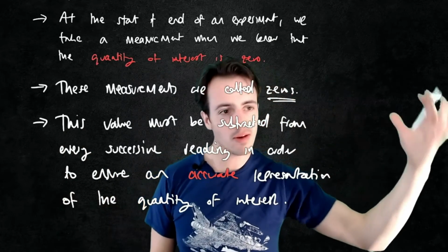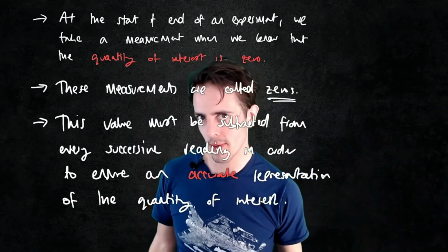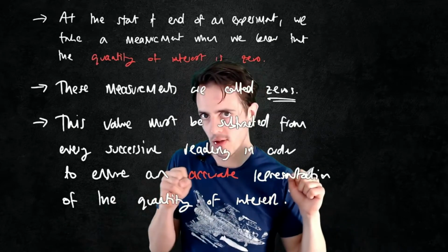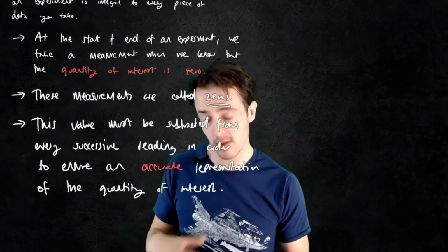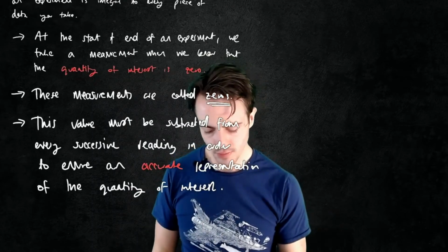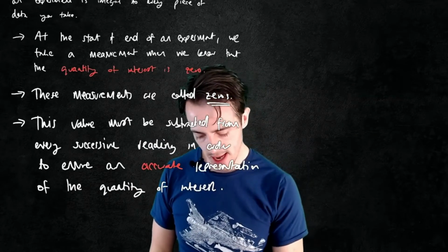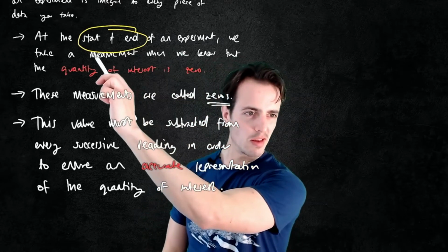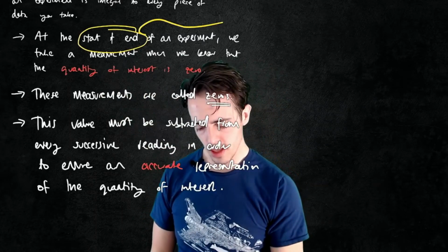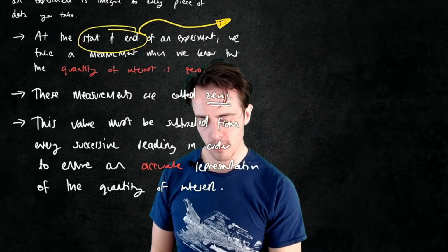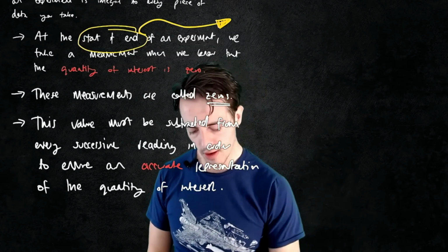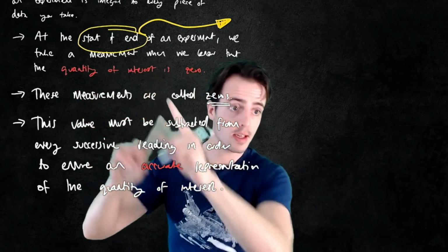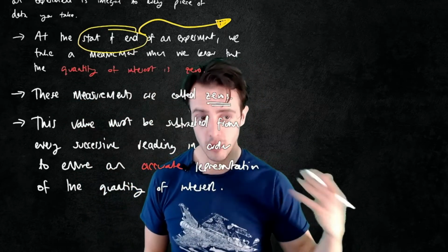And again, that example of standing on the weighing scales to measure your holiday suitcases might sound trite, but it genuinely indicates what this whole procedure does. And I set up here that we take maybe one at the start and one at the end. For this experiment, we've only taken one at the start. We're not going to bother with the end one because they aren't real data. But the reason why we do this is because any differences between the zero from the start to the end can indicate whether you've got an equipment failure.